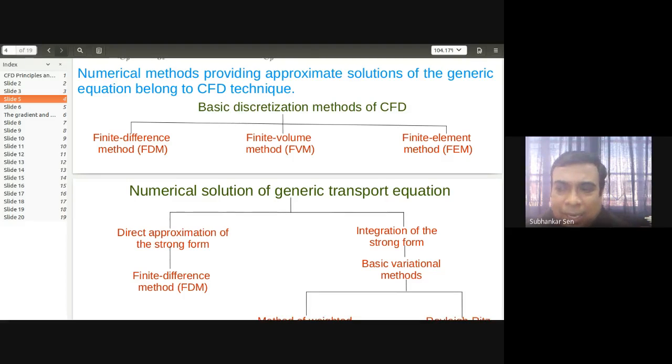I understand it is difficult to visualize from discussion. If I had a picture, it would be easier to explain. Still, the finite difference method does not operate on an unstructured grid. It needs a structured grid. This is a compulsory requirement.